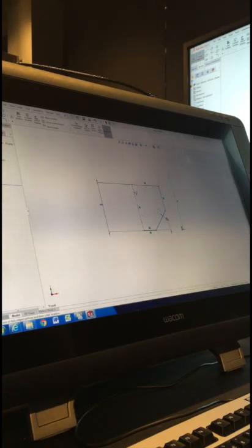I'll have a go. First up, the outside dimension. Here's a little trick I'll show you. It's to do with a construction line, which is going to be the center of something that you might revolve around, like the center point of a hole. I can dimension from this outside line to the construction line. That will be a radius, because I'm going halfway across the circle. If I move my cursor to the other side of the construction line, I'll get the diameter, double.